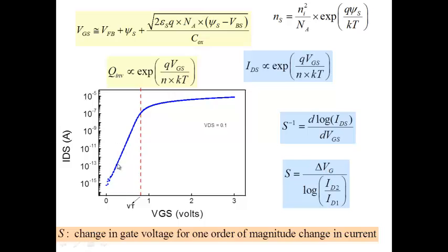That's what I said, the slope is relatively fixed. You can't alter it much. The actual value of the slope, we'll derive in a minute. So 60 is the absolute minimum. Typical values are 85 or 90, around that value. So this is like 90 millivolt per decade, and relatively constant, it doesn't change that much.